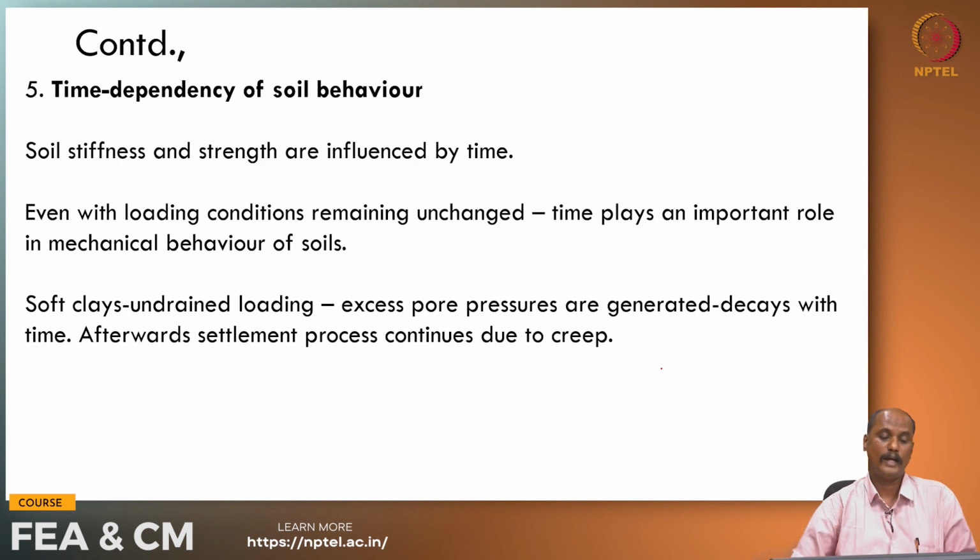When it comes to the time dependency of soil behavior, the soil stiffness and strength are mostly influenced by time. Even with loading conditions remaining unchanged, time plays an important role in the mechanical behavior of soils. Especially in the case of soft clays or undrained loading, the excess pore pressures that are generated decay with time. Afterwards, the settlement process continues due to creep. So, we have to understand the time dependency of soils to correctly capture the behavior of the soil in the form of modeling.